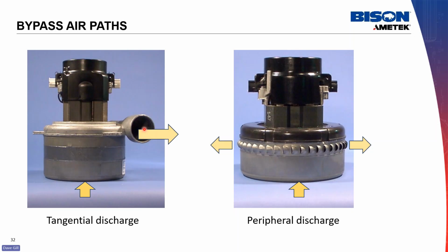It is useful when the pressurized exhaust is needed to do work. That way you can guide it and put that pressurized air where you want it. Or if the designer just wants to specifically duct the exhaust air away. For instance, if you're familiar with central vacuums, you will often see that the installer will guide that air to exit outside the house.